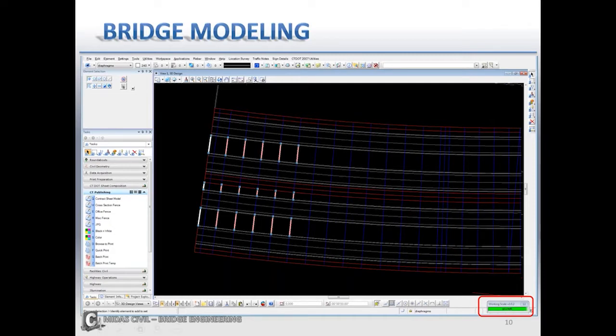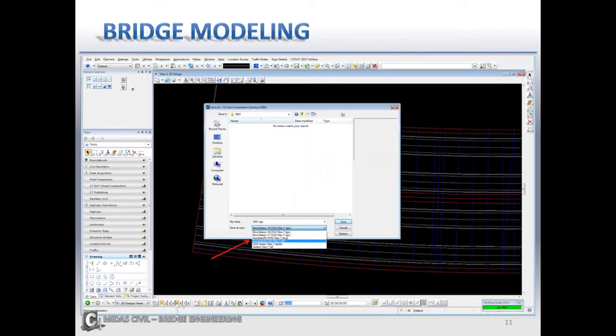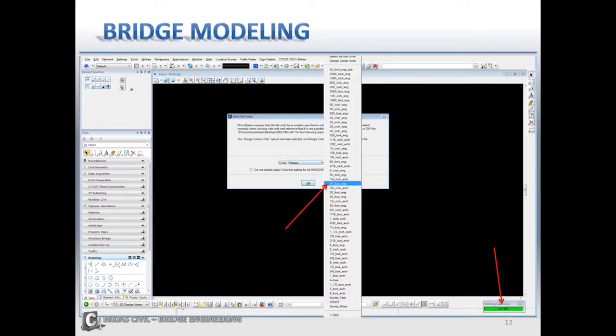Now you're also going to want to know what scale you work in. This is very important because you're going to do a file save as, and you're going to select DXF file. Now if you're using AutoCAD, you can skip this whole step basically, but then you're going to have to pick the units that you use to create the model. So these will have to match up in order for the scale to be proper. These also have to match up with your MIDAS model.